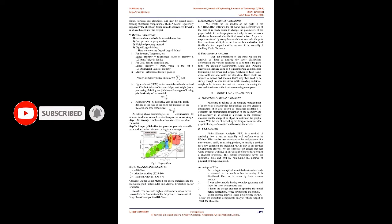1. Cost per unit property method. 2. Weighted property method. 3. Digital logic method. Here we are using the digital logic method. 1) For strength, toughness, etc., scaled property equals numerical value of property x 100 divided by the max value in the list. 2) For cost, density, corrosion, etc., scaled property equals min value in the list x 100 divided by the numerical value of property.